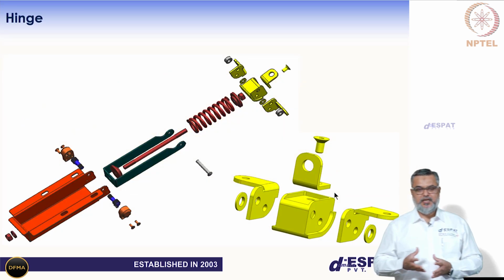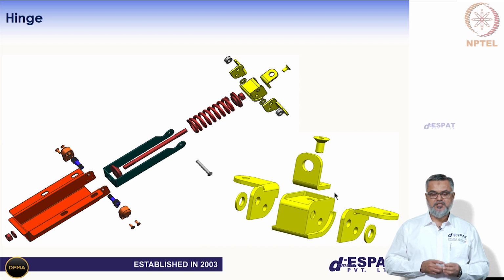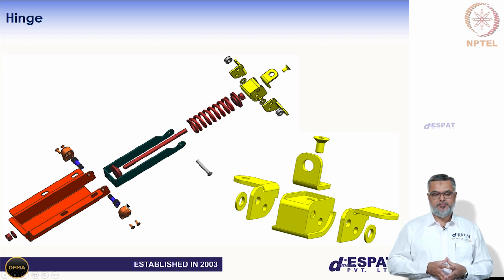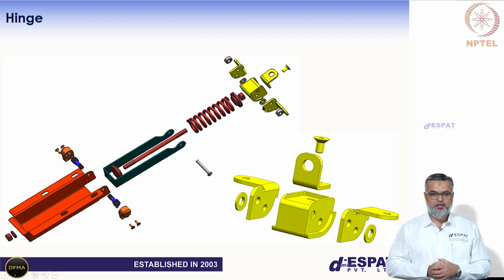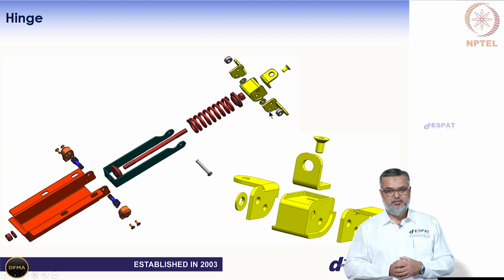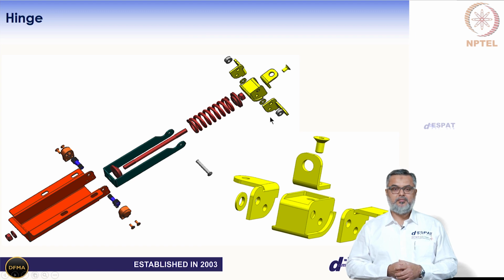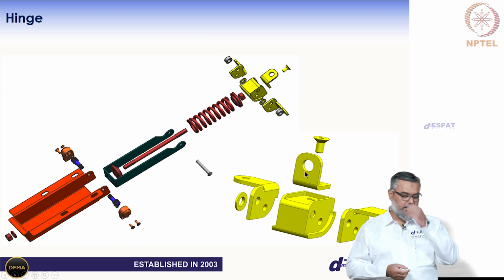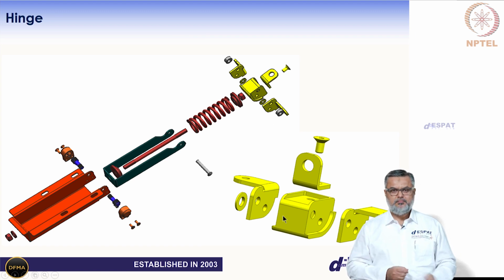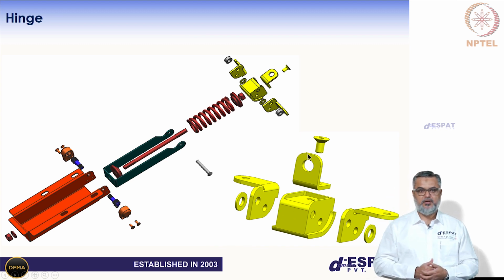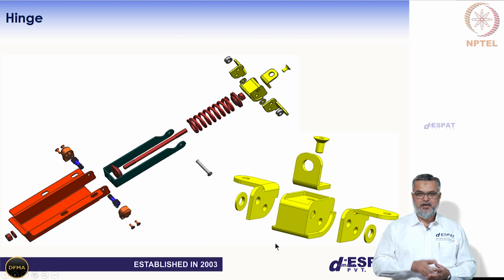So, we would say if you consider your product, look at what is probably the low hanging fruit that you could start to deploy DFM on and investigate for results. Like in this case, we are highlighting a hinge assembly for use in an enclosure. If you look at the bill of materials and look at the head of that hinge assembly, it looks like a good candidate for exploring part count reduction.